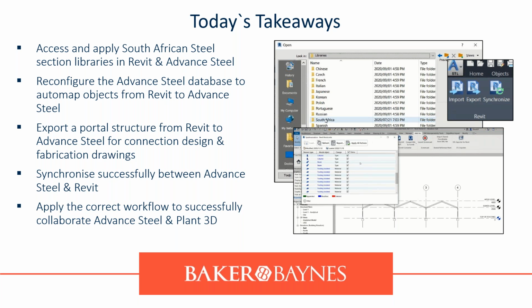Then you would need to auto map if you want to save time so that you don't get the pop-up to manually map sections coming in from Revit to Advanced Steel. You can do that by simply bumping up the UK sections to a number that's high. So I use 600. You're more than welcome to use that as well.